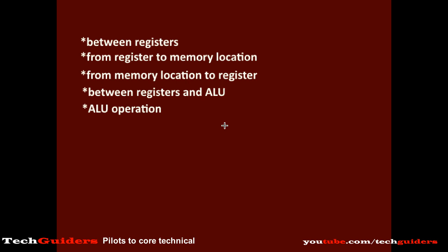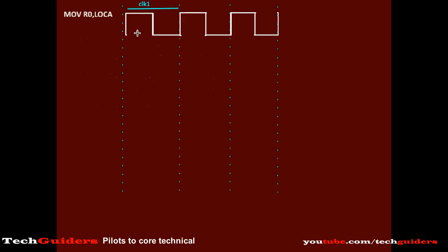So we can consider every instruction to be consisting of a set of one or more of these operations, which are executed in a proper sequence with the help of the control signals generated by the control unit. Also, the operations corresponding to the instruction are executed within time periods called clock cycles. So by producing proper control signals at proper clock cycles, the data movement corresponding to the operations of an instruction is done in a timely and controlled manner.